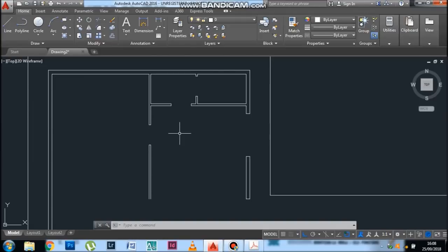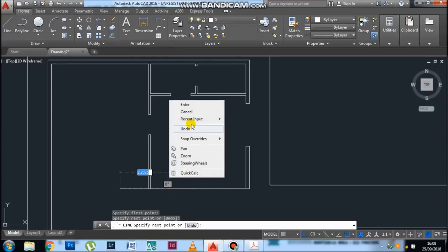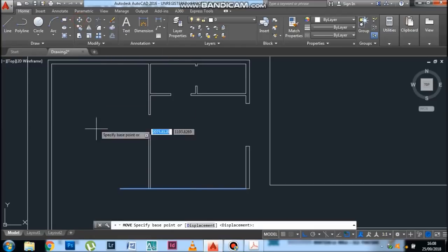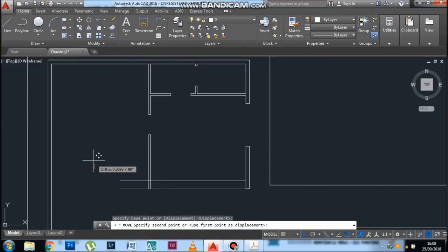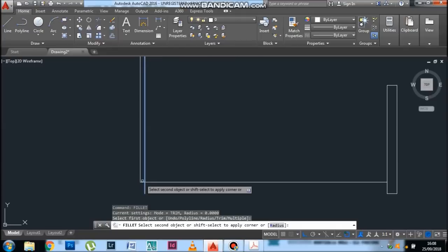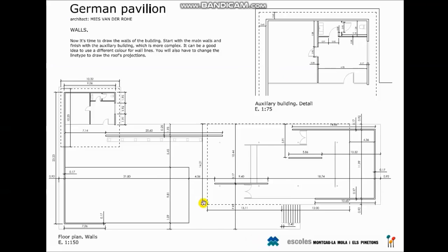And that's it. I see that there's a dimension missing here because you don't know where this wall has to end. So what you can do is just take the end of this wall as a reference, okay, and make it. I'm going to move this line just 20 centimeters shorter, so 0.2, and you can make it this way, okay. And that's all. We have the plinth and we have the walls.